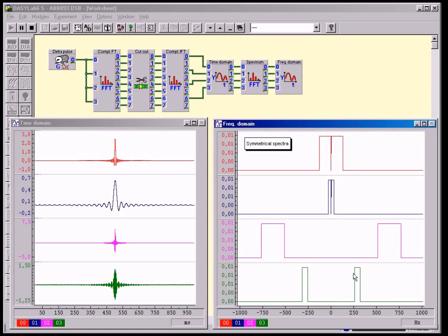In this range, all the frequencies, as in the case of the delta pulse, should have the same amplitude, so that the Ft directly produces the transfer function. All the frequencies should be present simultaneously, so that, unlike the sweep signal, the system to be tested can respond at the same time to all frequencies.